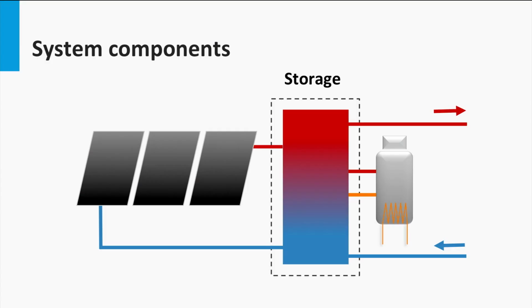The next element that we are going to consider in the solar water heating system is the storage. Energy storage has an enormous influence on the overall system cost, performance and reliability. Its design affects other basic elements such as the collector or the thermal distribution system.